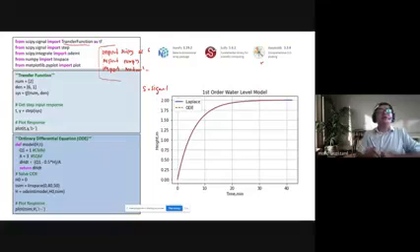I think most of us understand this information if you're very well versed in MATLAB. Basically 2 is the coefficient of the numerator, and 6 and 1 are the coefficients of the denominator in polynomial form. Then you just want to understand, if you have this transfer function, what the response would look like for a step input. In this case I just use step.